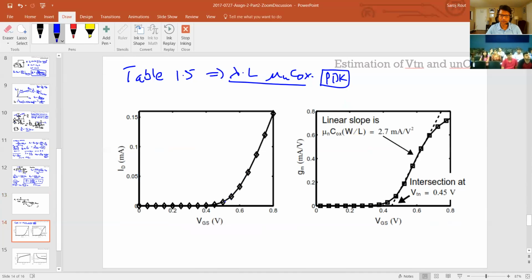If you take a transistor and plot ID versus VGS here, we showed that it was a nonlinear equation, right? But if you extrapolate this point over here, it roughly gives you a threshold voltage VTN. So you can take a transistor, bias it, and sweep the current, and that'll give you a VTN. Then use this VTN for your hand calculations. It's not going to give you the most accurate answer, but it will guide you to pretty much 90 to 95% close to whatever you're trying to achieve, and then you can simulate after that, okay? So that'll give you VT.